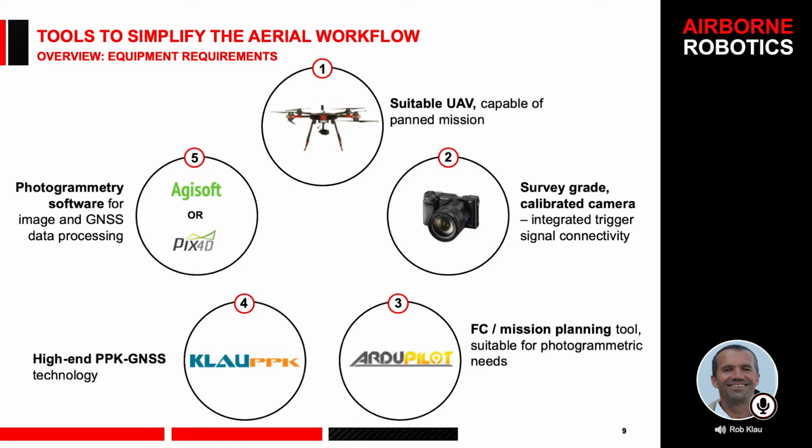And that's how we can approach that claim of saying you don't need GCPs. That traditional way of having GCPs and reverse engineering camera positions and lens focal lengths and all of that goes away. So now it's a forward engineering process with quality data, and it actually makes your life easier because the processing will happen in half the time with quality data.